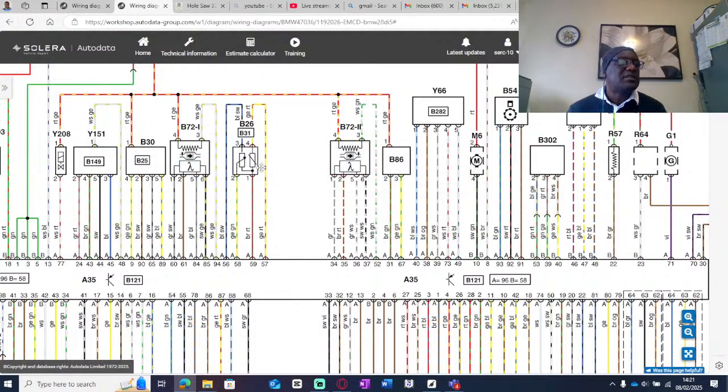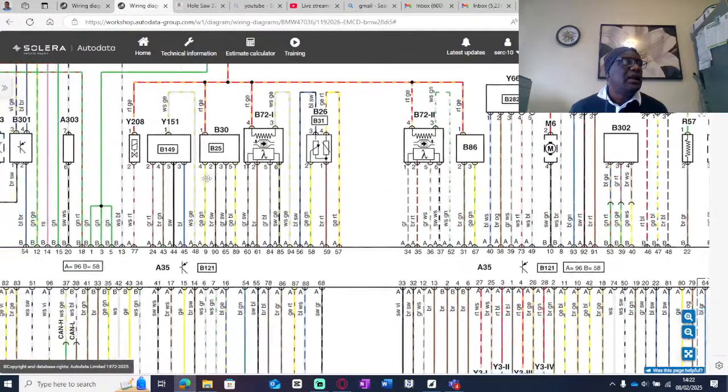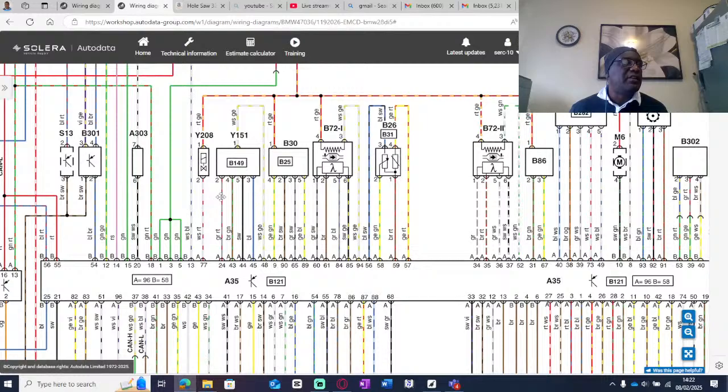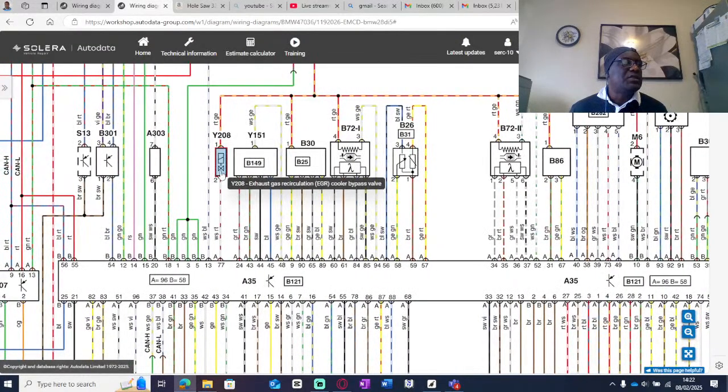And let's look at this one here. That's your fuel system pressure sensor. Here's another symbol that I want you to familiarize yourself with. It's a solenoid. You see that one there? I want you to understand what that is. When you see that symbol there, that's a solenoid. Some of the petrol injectors will have that because they behave the same as a solenoid.